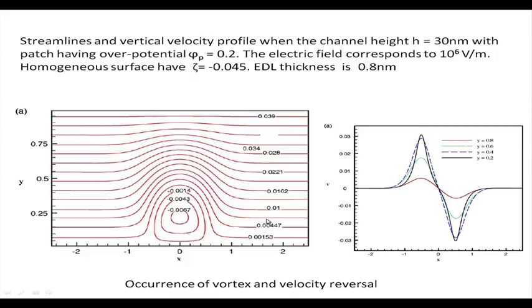So this is very advantageous in several situations, particularly in mixing of solute in the nano channels or micro channels where turbulence is absent. Okay, there is no chaotic mixing because of the low Reynolds number. We don't have any chaotic mixing in this kind of micro channel or nano channel, but by imposing the surface heterogeneity, one can get a recirculation vortex development, and that improves the mixing.